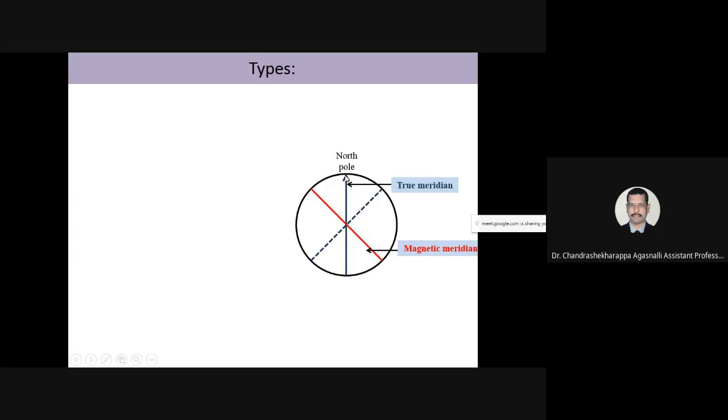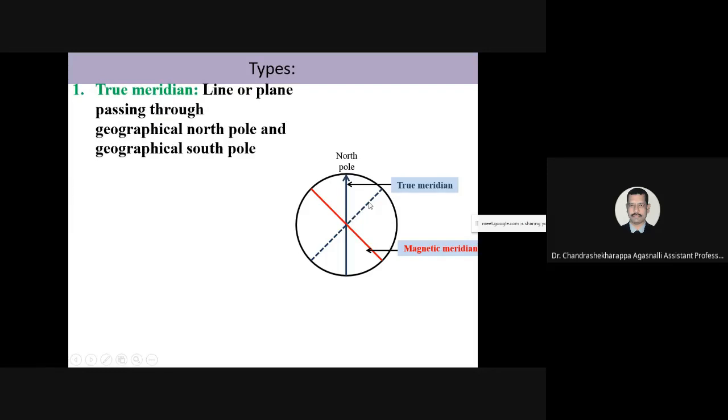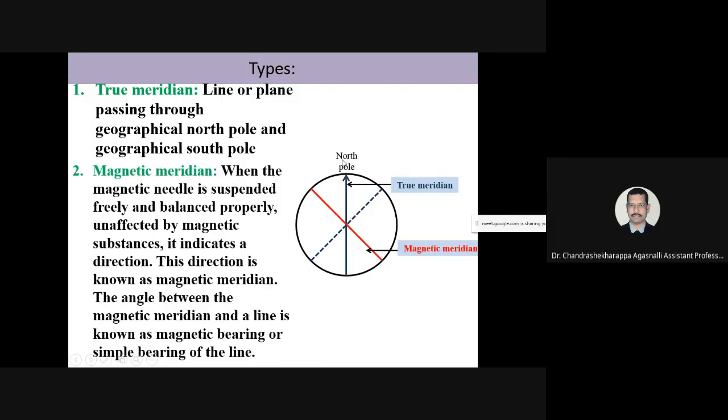If you say north 45 degree, this means it is measured from here only. North 45 degree here. So automatically it will be a south 45 degree. This is a direction, the main straight line of this. If you are reading north 10 degree east, south 10 degree west, or north 50 degree, anything you can read, but when you are writing that, you write it properly.